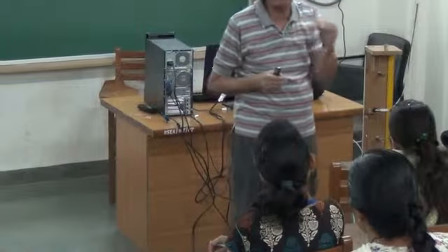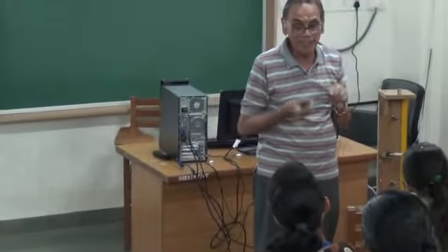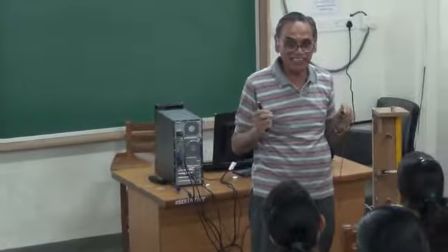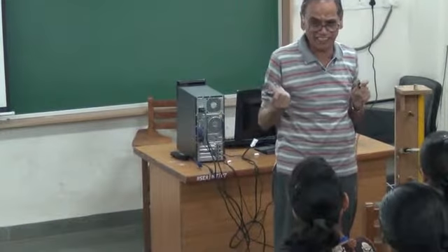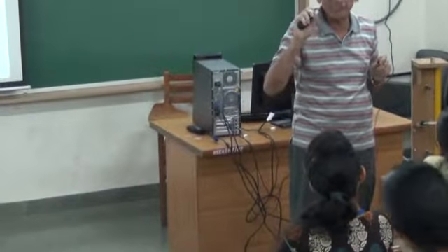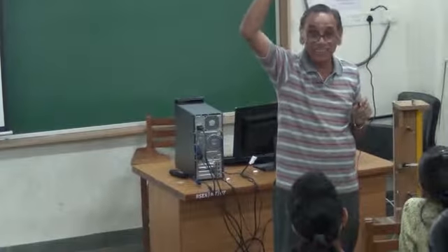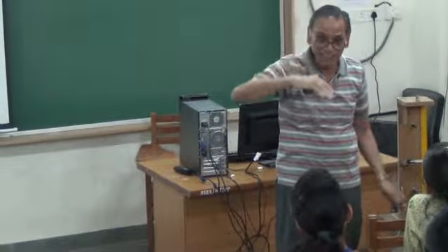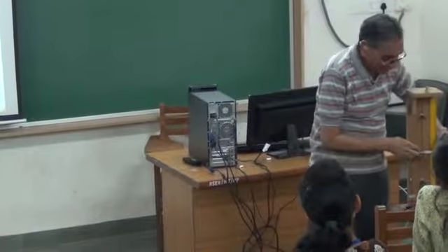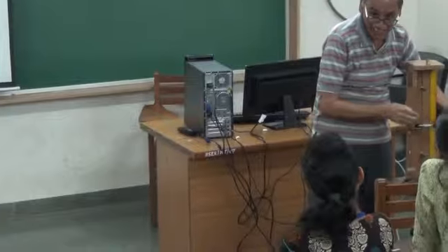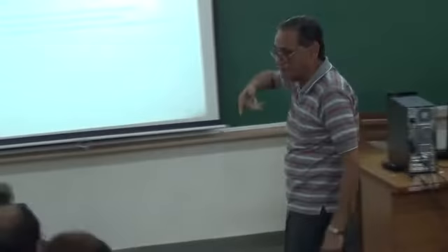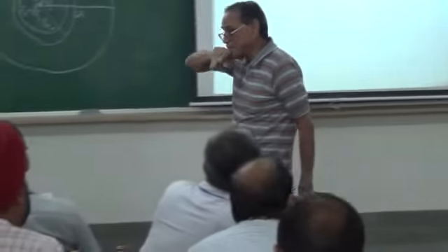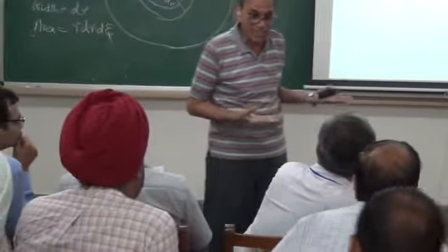I take the power cable, connect it to the output of my power amplifier. The input is connected to the signal generator. I give some voltage at the signal generator, 2 volts, and I change the frequency. I again start with the high frequency and I lower the frequency. Then you will see that these will start oscillating back and forth, and at resonance the amplitude will be maximum. So find out where you get the maximum amplitude and note that frequency.